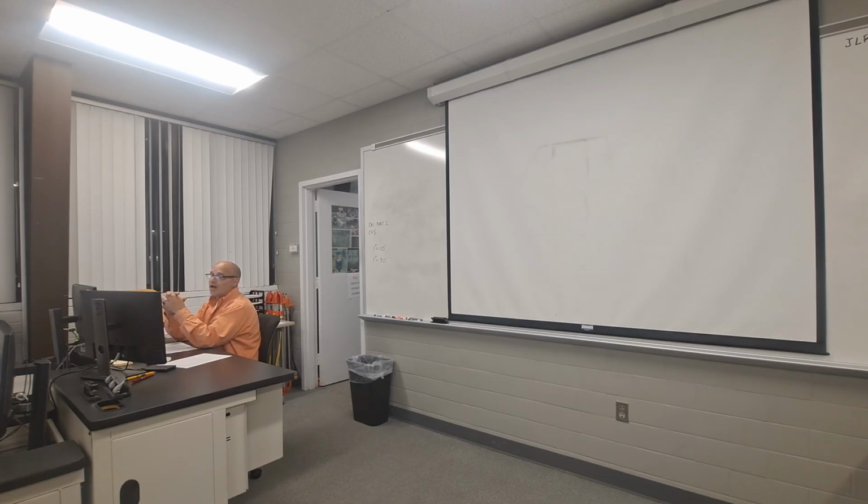You will not go smaller than 1 inch equals 10 feet. So if you end up 1 inch equals 10 feet and it still looks kind of small in your border and title block, check your scale to make sure, maybe look at somebody else's and see if theirs is small too. But don't go through and build another scale, 1 inch equals 5 feet or 1 inch equals 2 feet. Stay with the standard scales that I put on that drawing factor sheet for you. So once again, your scale is gonna be the biggest as it can be.